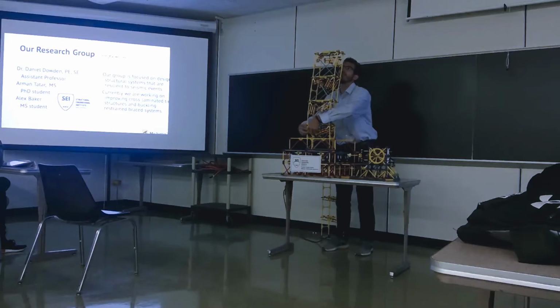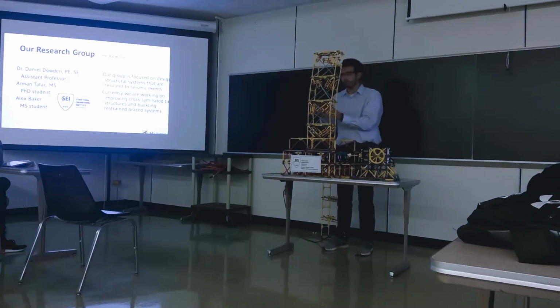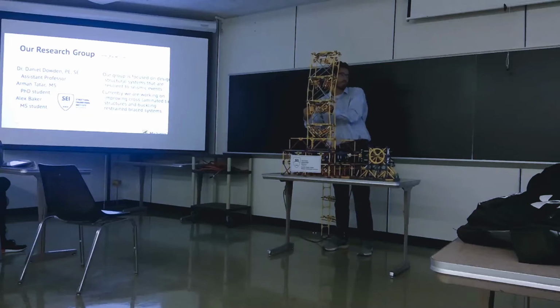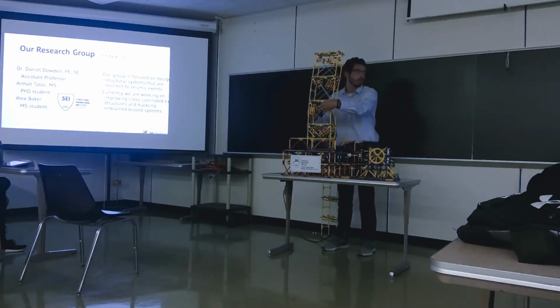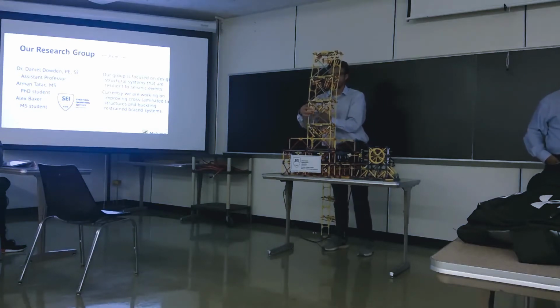It's fun. I could add more mass to increase the force in the system. I could have more floors to increase the second order effects, the P-delta effects. So where do you think is the maximum displacement in this system? The high floors or the low floors? You're talking about relative between floors, inter-story? No. Overall cumulative displacement. Well, if we're looking at his first model, it seems like if you're looking at the low frequency, the high floors are the ones that seem to be displacing the most.